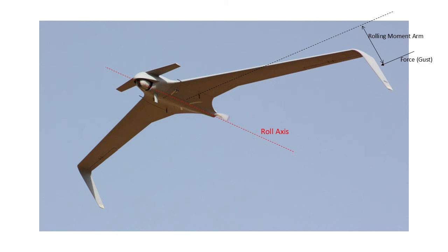In a similar manner, in a side wind condition for an upturned winglet, say blowing from the left to the right, the upturned winglet will have the aircraft roll rightwards or away from the wind and yaw to the left or into the wind. Alternatively, for the downturned winglet, the same wind will cause the winglet to roll the aircraft left or into the wind and also yaw left or into the wind. So this is great for static stability. It's pretty cool stuff, even if downturned winglets are impractical sometimes just due to non-aerodynamic constraints.